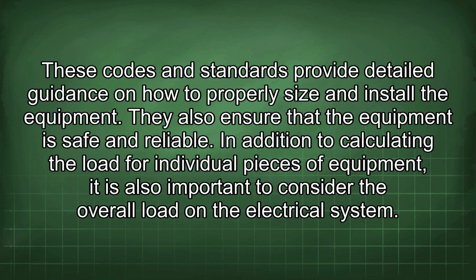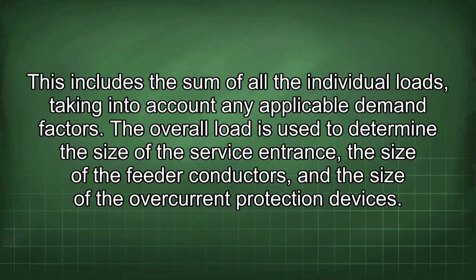In addition to calculating the load for individual pieces of equipment, it is also important to consider the overall load in the electrical system. This includes the sum of all the individual loads, taking into account any applicable demand factors. The overall load is used to determine the size of the service entrance, the size of the feeder conductors, and the size of the overcurrent protection devices.